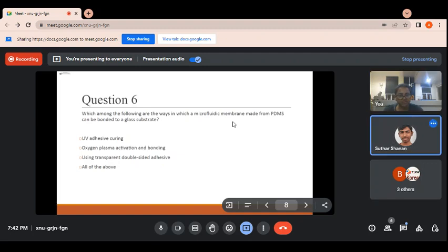Yes, ma'am. So basically, we will create the mold using various techniques, using photoresist and UV light and developing. We will create the mold, and after that, we will deposit the PDMS such that the PDMS spreads evenly in the mold.